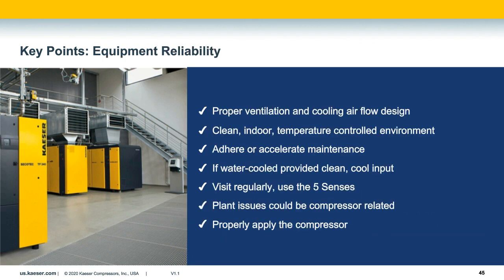So don't shy away from this type of analysis, but keep in mind that operating conditions in the compressor room will have a direct effect on the reliability of your compressors and compressed air equipment. Applying the recommendations we've discussed will ensure that your system is reliable and efficient. So, ventilation, ambient conditions within your room, performing the maintenance, or actually knowing what the maintenance is. Is it severe duty or is it regular duty? What maintenance schedule do you need?